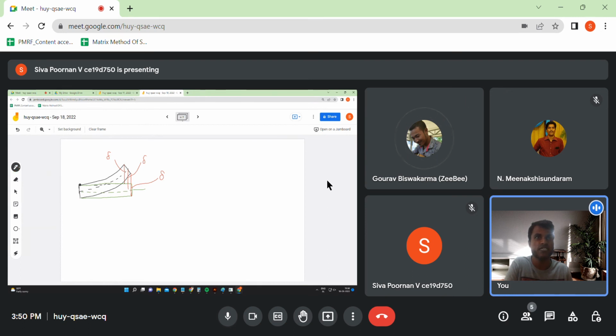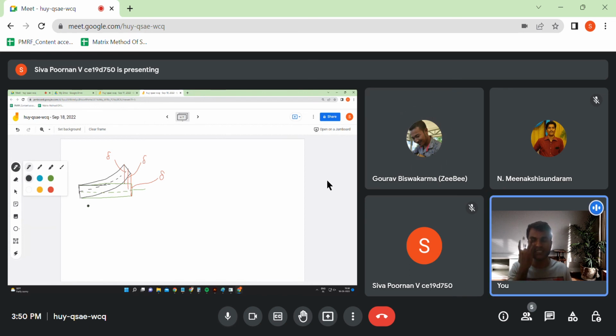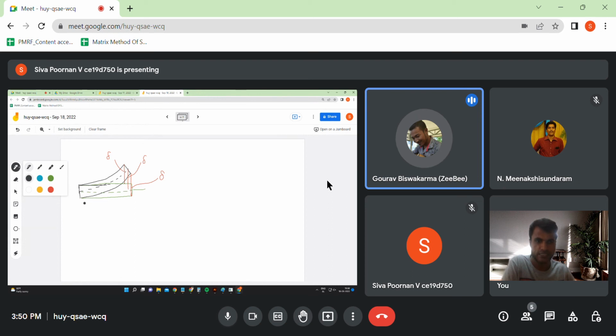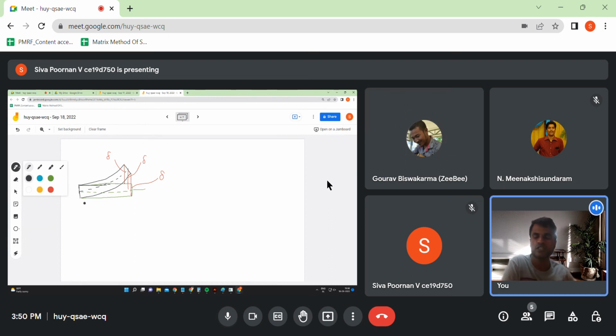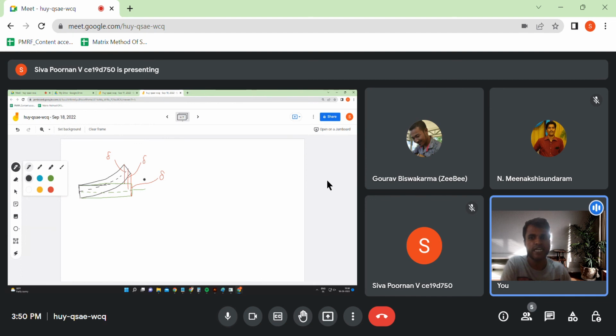When you have the initial thickness of the beam and the final thickness after bending, we assume that both of them are the same. There is no strain along the z direction. By z I mean the thickness direction. The cross-sectional shapes will be conserved; the cross-sectional depth will not change before and after bending. This directly says that the deflection of each of these points is going to be the same. You can directly find this out. It's not very difficult. Even geometry-wise, you can show that the deflections of all these points would be the same if you only have longitudinal strains.